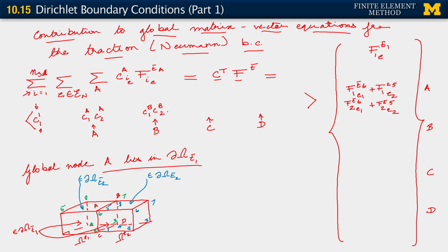The CB1 contribution on that node is 0, there is no contribution to the traction there, we are not controlling the traction there. But that's a free surface, because that is a surface on which a traction may be specified, we've just not specified the 1 component there. So when it comes to the B node, we get a 0.